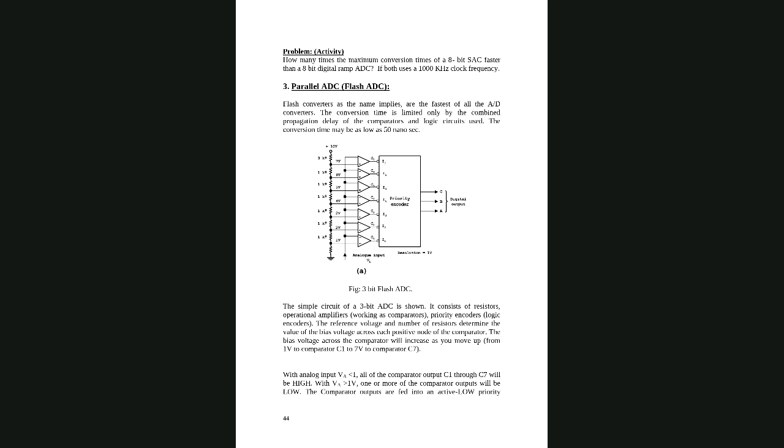So my point is very simple. First of all, you see the total voltage, you see the resistors, and you find all these positive terminals. This is the first step you should do, by closing your eyes. Very simple. You will apply the voltage divider rule and you will find it. Then based on the input, you know the comparator. I told you how a comparator works. We are considering the comparator output before the bubble, don't look at the bubble now.